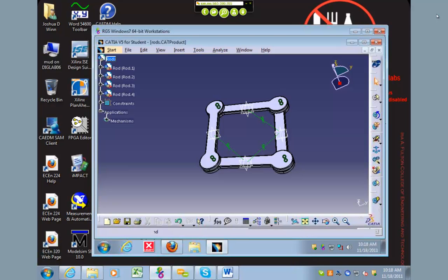Translation in what sense? In the sense that if I have a mechanism here, I can rotate in one direction and I can translate. So that might not necessarily be the direction that I'm translating it in, but it just allows that degree of freedom. So why would you want us to? Well, in that case, it allows me to take this piece and slide it down this face if I wanted to. So like I could create a bar slider. Okay, so once we've defined all of the joints,